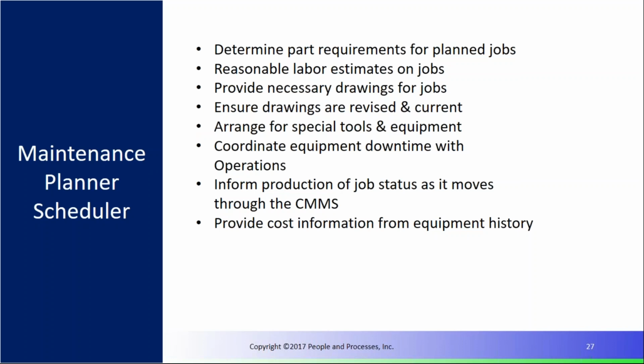So you want to think about it from an analytical estimating standpoint. If I take this particular job, maybe it's replacing a pump. How do I do that? What are the task steps? Well, I might need an electrician to come over and disconnect the motor. Then we've got to break the coupling, and we've got to do some other stuff. And so you eat this elephant one bite at a time. That's really analytical estimating. How much time for the electrician to lock it out, tag it out, unhook the motor? Then they disappear. The mechanic deals with the rest of it, and then I need the electrician back for 30 minutes to hook back up the motor, or whatever the case may be.